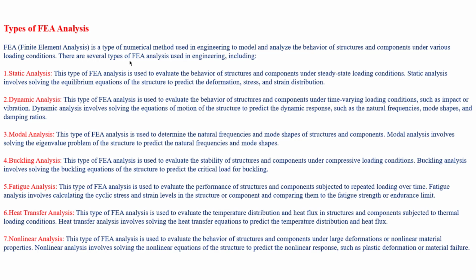When it comes to FEA, we have the static structural analysis. Here we're going to find out the FOS, factor of safety, stress, strain, and displacement results, and then we'll decide whether our results are fine or not by using these. The dynamic analysis: here there are two things, the time based and the frequency based. In the frequency based we have modal analysis, random vibration, harmonic, and seismic analysis.